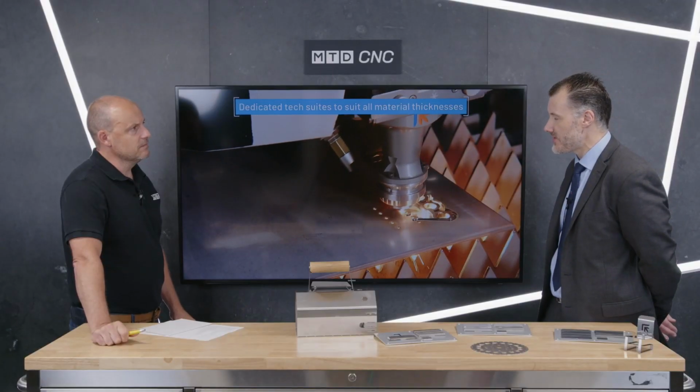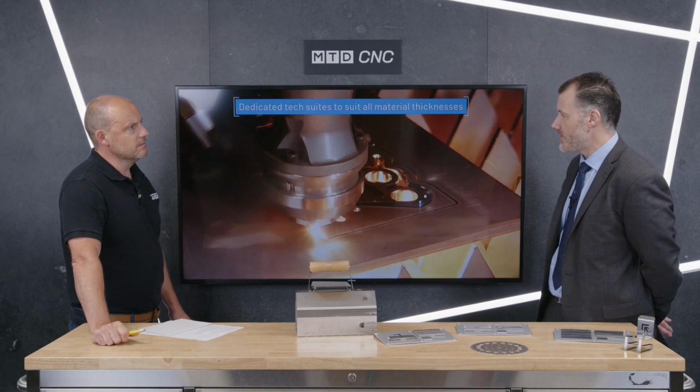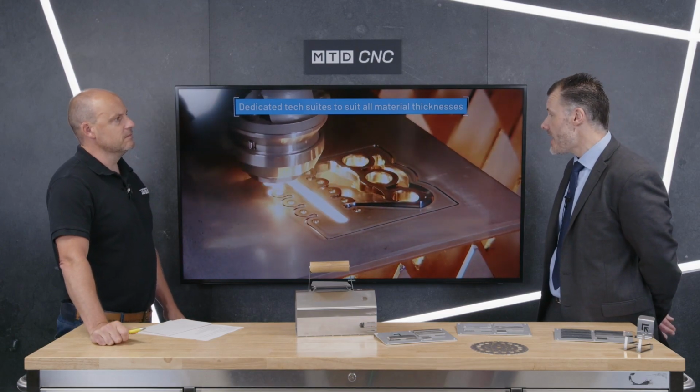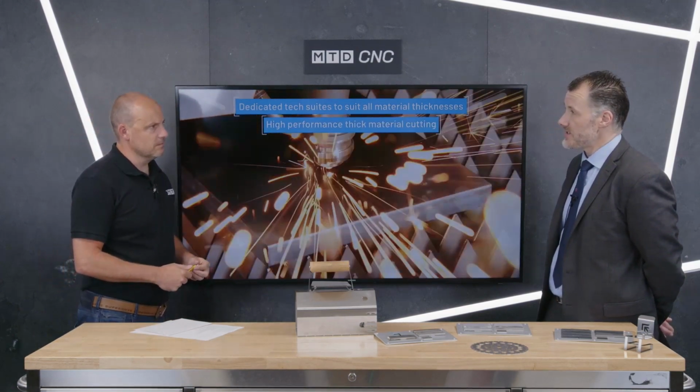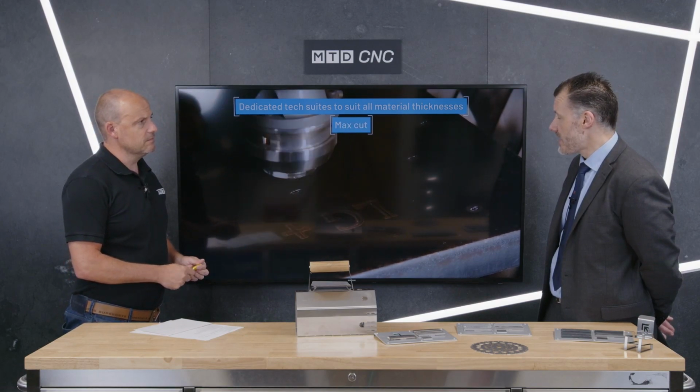Because, as you've just seen there on that video, with laser, sometimes you cut a piece out and it could quite happily flip up out of the material. So the head is designed and the software is designed to avoid going over areas where that would happen. And from that point of view, if the head does have a collision, it's very, very simple to reset. There's no real damage that can happen from it because the head simply disengages.